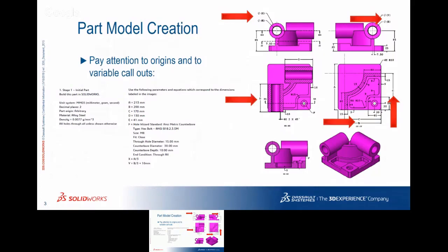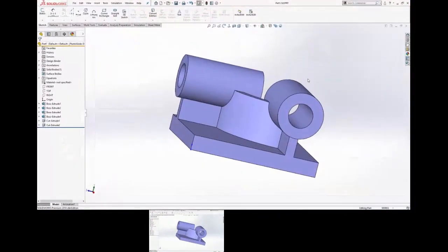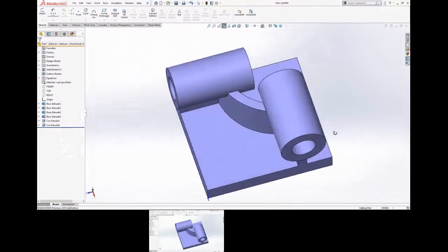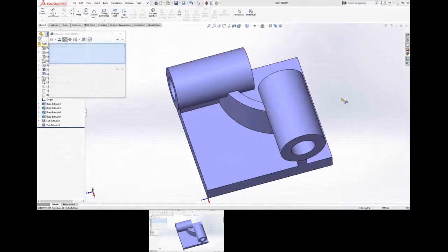The way you could have reflected it about a plane, you could have created a plane down the diagonal and then just reflected it. Yeah, they're different. That's the problem. Yeah, because I thought about that this morning actually. So he's asking, could we just mirror these two bosses? But if we look and see, the outer diameter is different.